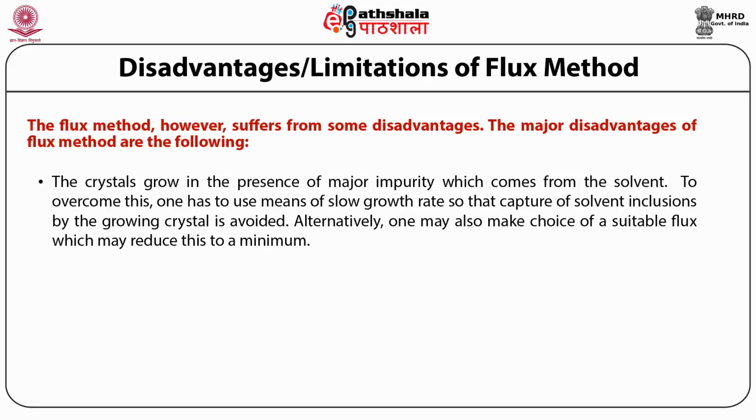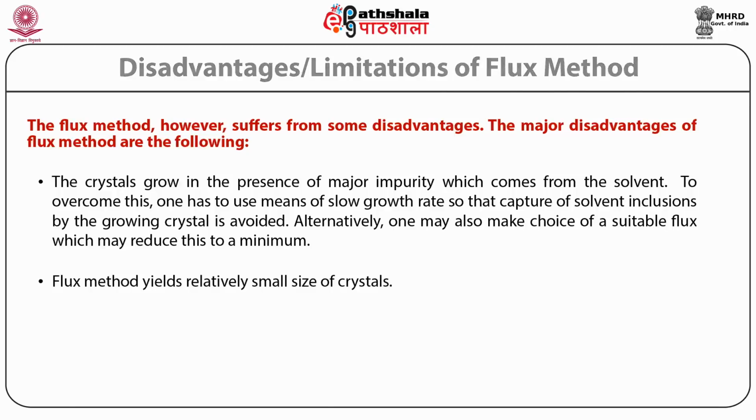To overcome this, one has to use means of slow growth rate so that capture of solvent inclusions by the growing crystal is avoided. Alternatively, one may also make choice of a suitable flux which may reduce this to a minimum. Flux method yields relatively small size of crystals.